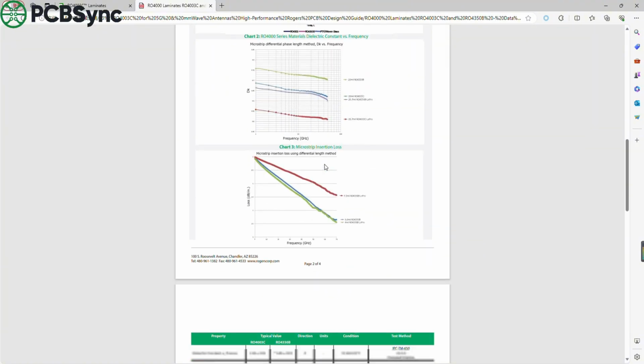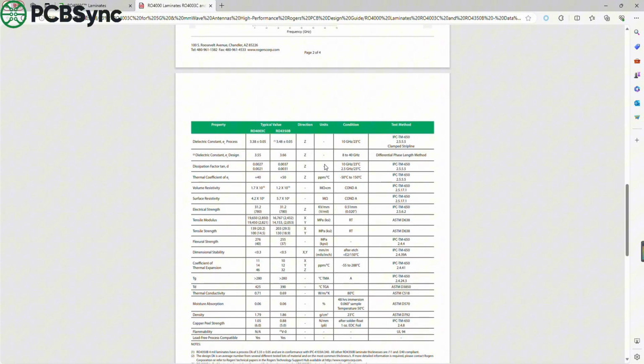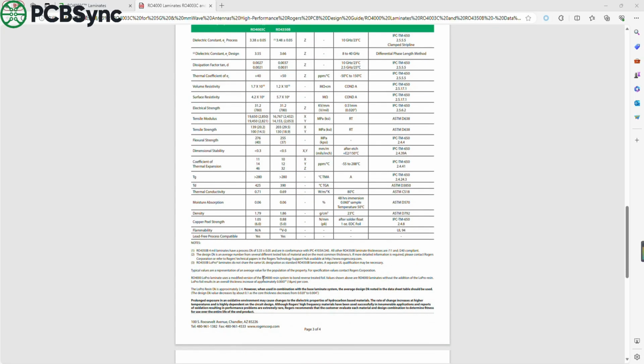In terms of manufacturing, RO4003 can use a production process similar to FR4 and does not require the special treatment needed for PTFE materials before metallization. However, in actual production, it is still necessary to customize drilling, lamination, impedance compensation, and profiling parameters according to the material's characteristics.